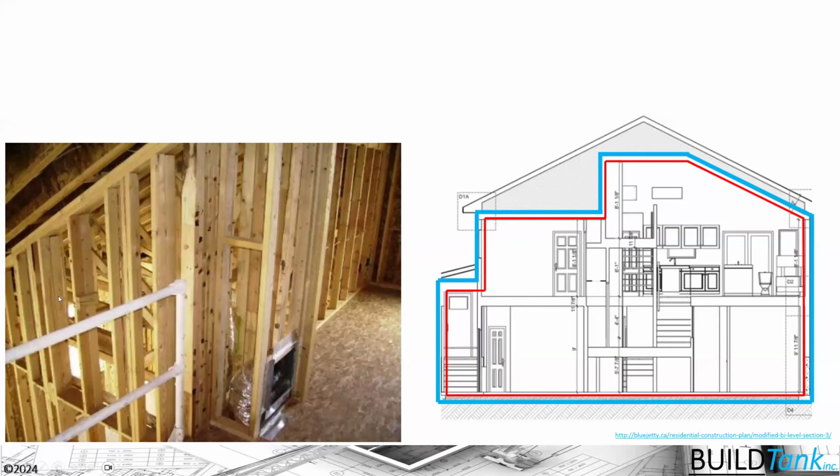And we're going to drywall on the inside, and the drywall is going to come around this duct chase and go down the loft wall here. And we've got enclosure of the insulation there. So I'm going to ask you real quick, is that duct inside or outside the building envelope as I explained it? Again, you can type an answer in the chat if you want to. But moving forward, I would tell you that the duct is not inside the conditioned space yet because we have misalignment of the continuity of our air barrier and our thermal control layers in this house.